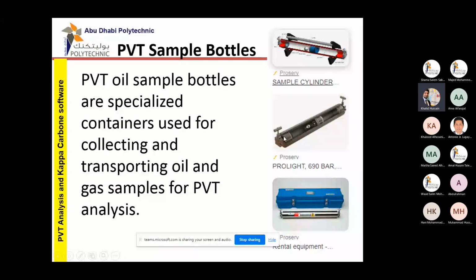ProServes are the manufacturer of PVT bottles. I just want to share here: PVT bottles have a piston inside. One side is glycol, like water, and the other side is the oil sample. When we transfer the sample from the chamber, the chamber has collected the sample at reservoir conditions, right? Temperature and pressure, and we transfer the sample from the chamber to the bottle.